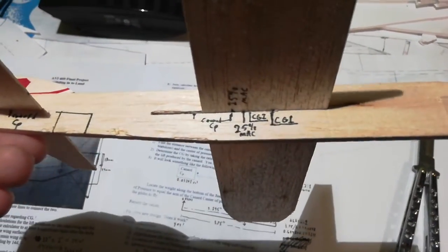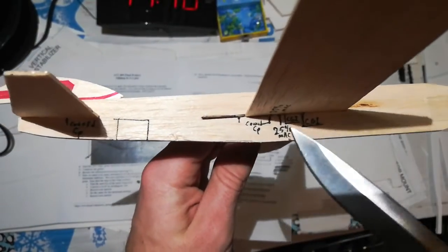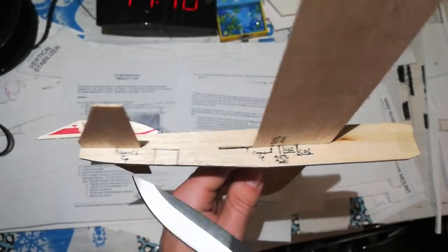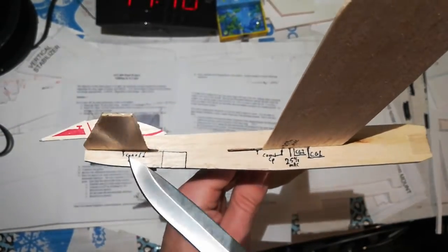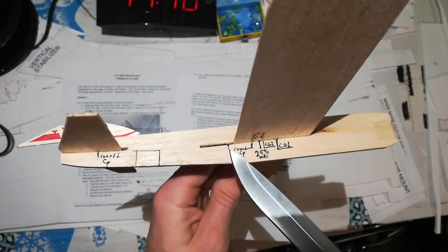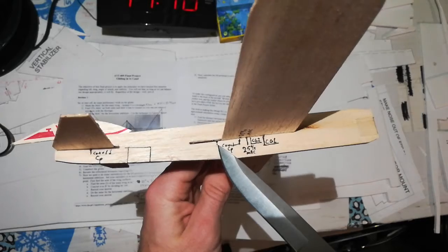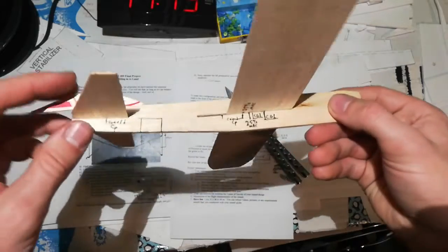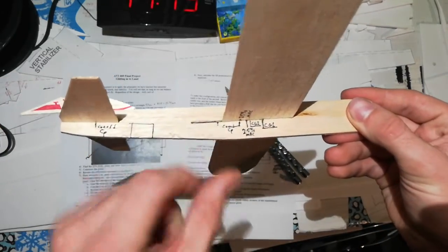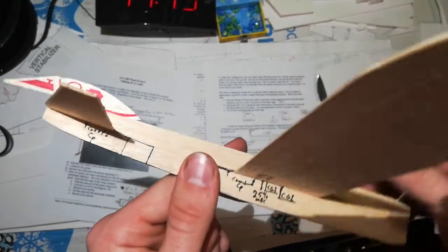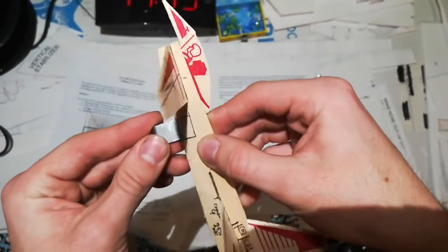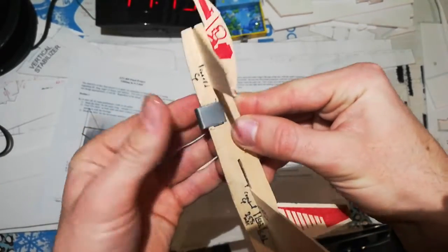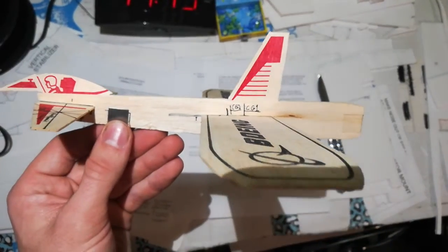So you can see we have the center of pressure for the wing is right here, and the canard center of pressure is right here, and 3.125 inches from there is where our center of gravity should be. So we need to relocate the weight to where our center of gravity ends up right there. And it just so happened to be that that weight, in order to create that moment where we need it to be, should be right here. So let's go give this a flight test now.